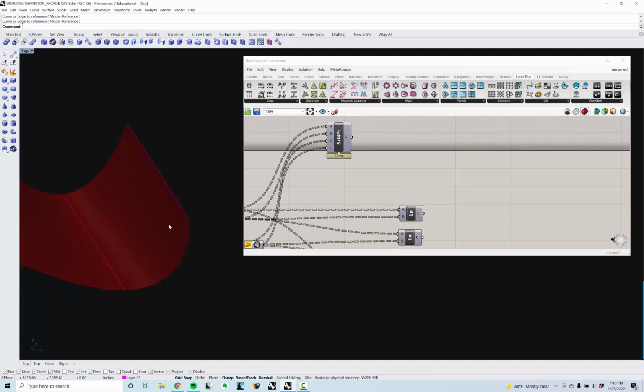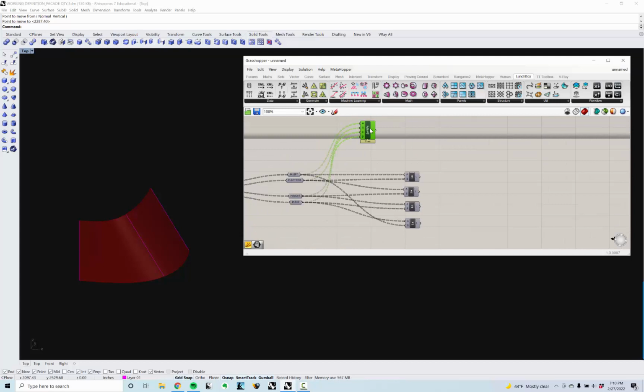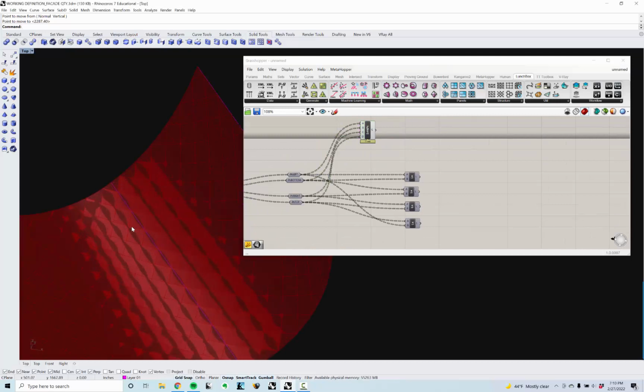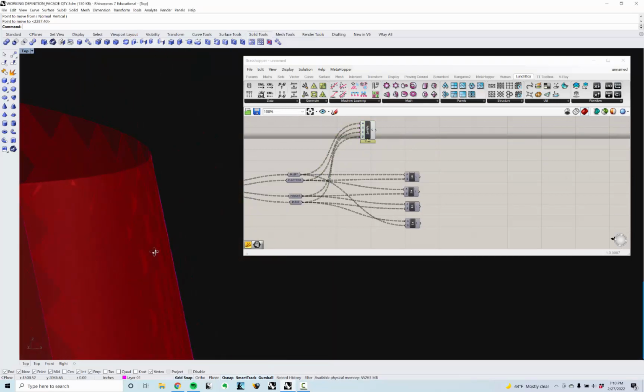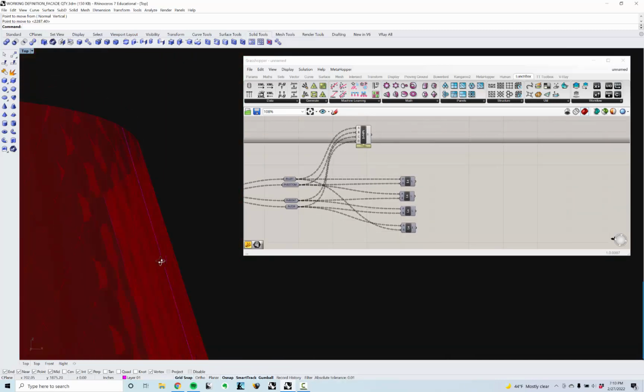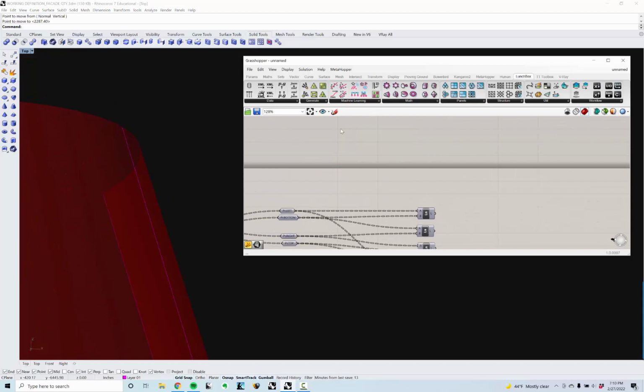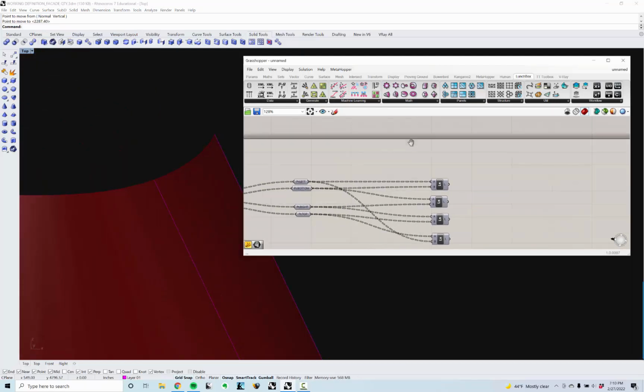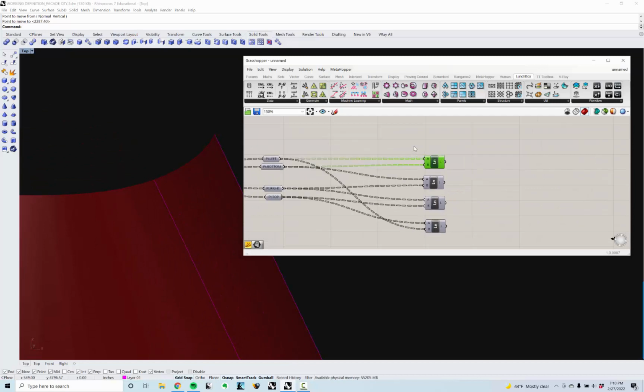So we're going to use this really funky looking surface for this. Let me just flatten it out a little bit so it's not too intense. And if I preview this, you'll see we have our 4-point surfaces, but these are actually curved, as we just illustrated with the flatness check. So I don't want there to be any curvature in my panels because I want to make this out of flat panels. So what I'm going to do is turn these back on.